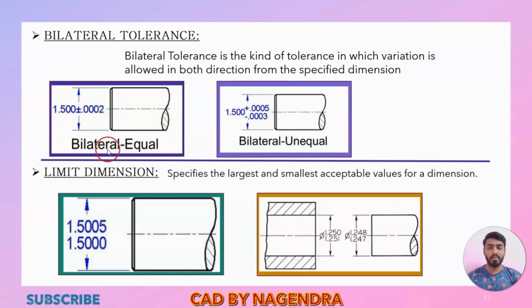Again in these, bilateral equal and bilateral unequal are there. Bilateral equal means the positive value is this value, and the negative side also is this value. With unequal dimension, the positive value will be different and the negative value will be different. Like that we need to mention these tolerance values.